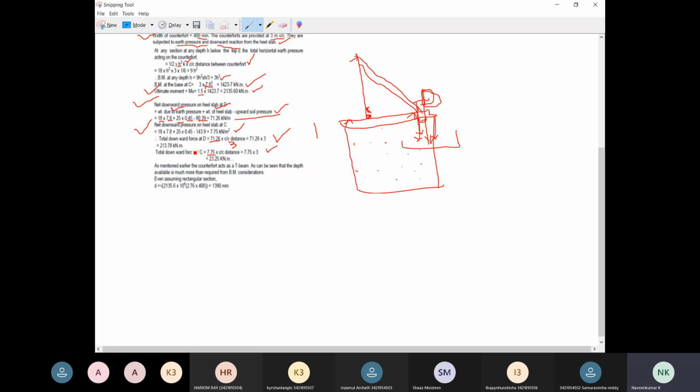It will give you the flange section bending moment formula. I'm repeating again the code book and the page number: IS 456 2000, page number 96. In case of flange section, there will be an expression for moment.